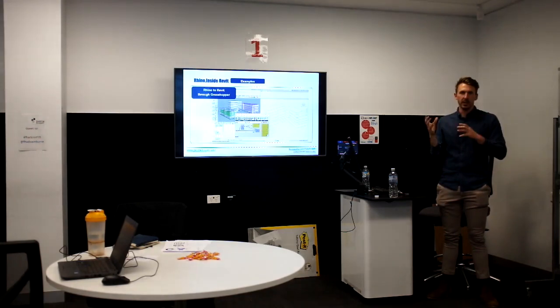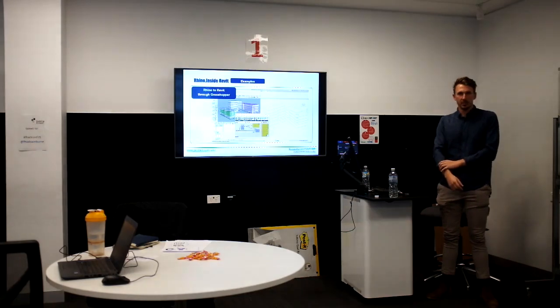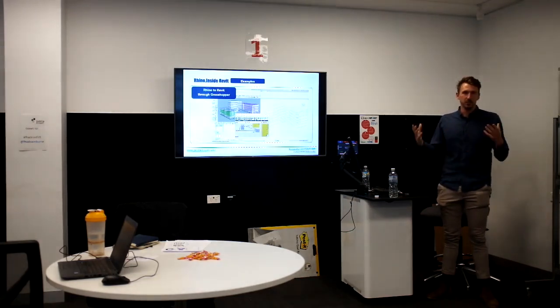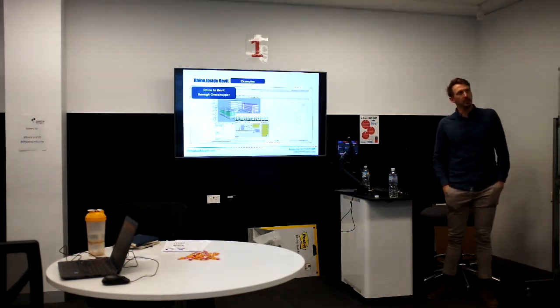So where we can, we'll create native Revit elements. For instance, a beam will get passed as an IFC beam, but it will create a native Revit beam. For more complex shapes, it'll create a direct shape. We're just using IFC as the transfer mechanism. It's still producing Revit elements. It's not a linked IFC.